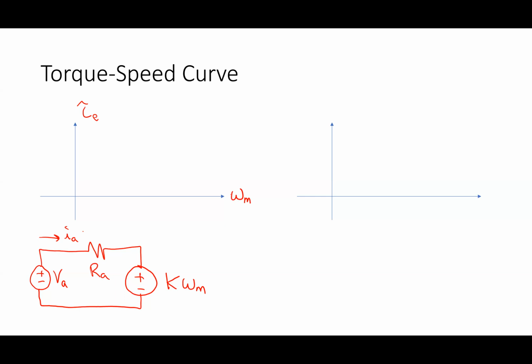Apparently the motor is stalled. It's putting a lot more current in than before, because it's trying to produce as much torque as possible to get this moving against my fingers. If I let it go, it'll start spinning again, because the load torque on it is significantly reduced.